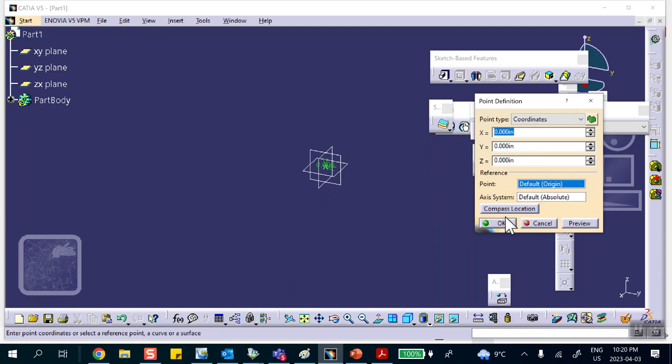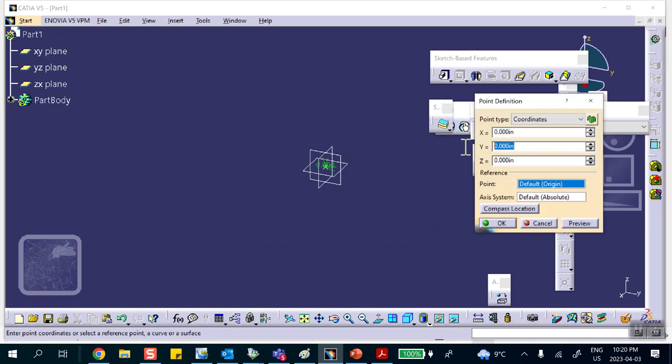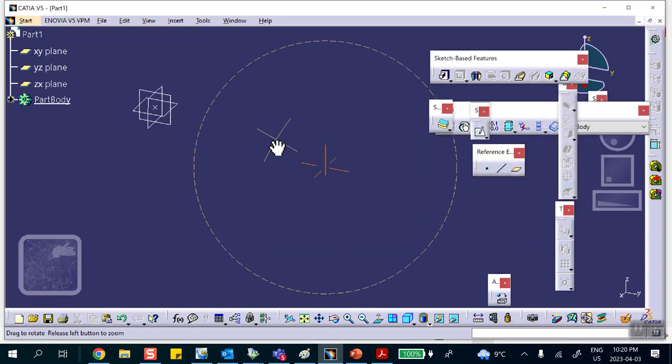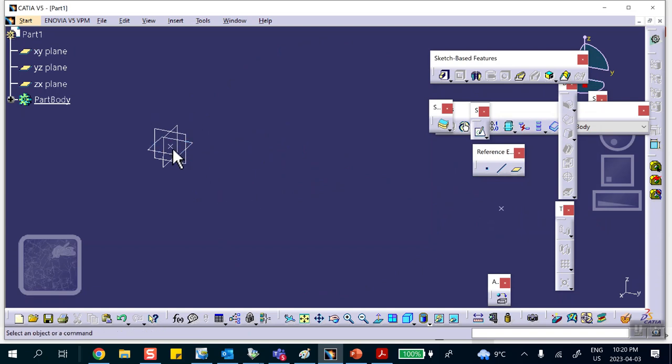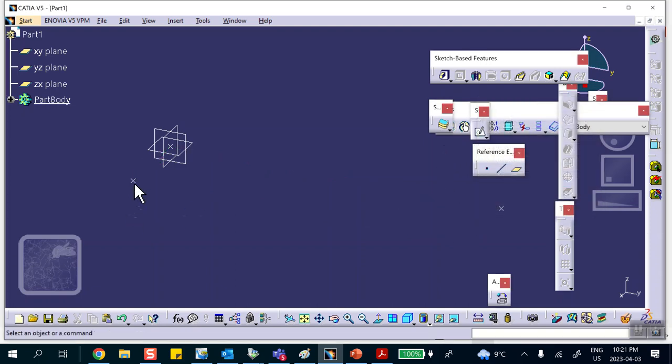We will define 3 points: one for one end of the beam, which is the wall, basically, then the other end of the beam, which is the free end. And finally, because the cross section is a square, I need an orientation point. So I'm going to choose any point which is off this line, for example x of 5 and y of 0. This point is going to be used as the orientation point.